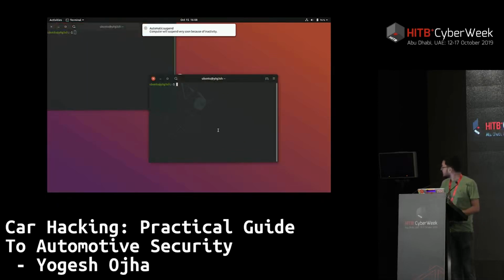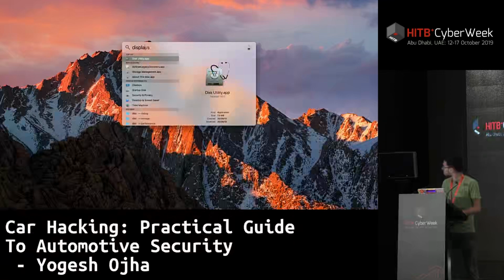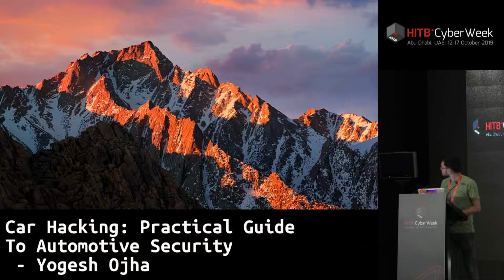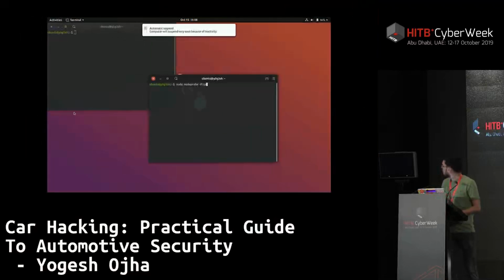I'm going to open two terminals right now. To do anything, first you need to have a virtual CAN interface, right? Since we do not have any virtual CAN interface right now, what we can do is load the kernel modules for CAN using sudo.